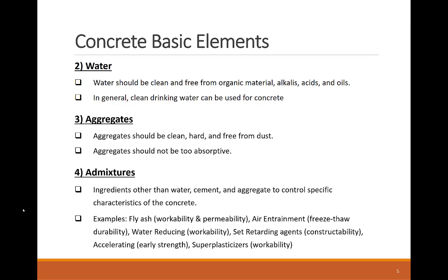On the other hand, air entrainment is the process whereby many small air bubbles are incorporated into the concrete and become part of the matrix that binds the aggregate together in the hardened concrete. Air entrainment additives and their created air bubbles increase the freeze-thaw durability of concrete.